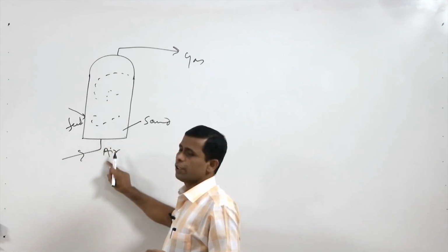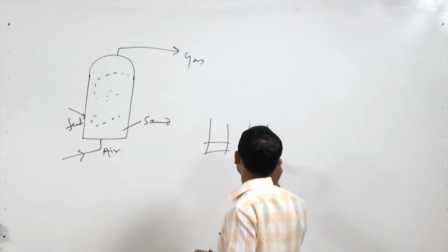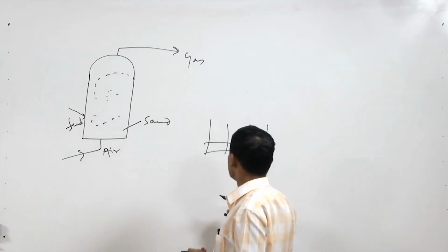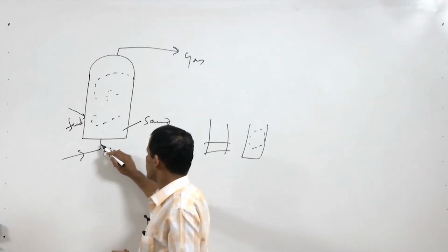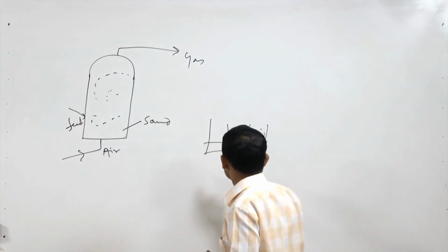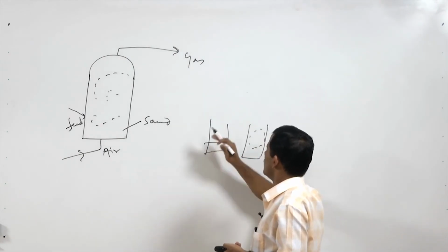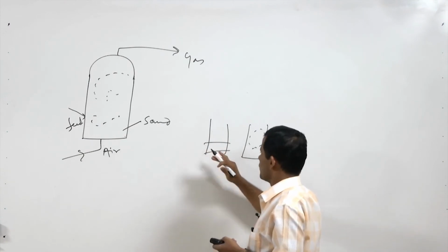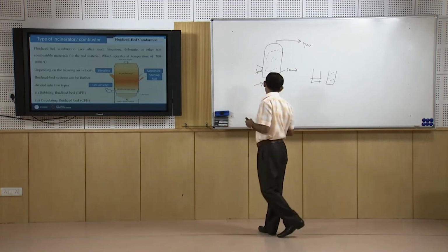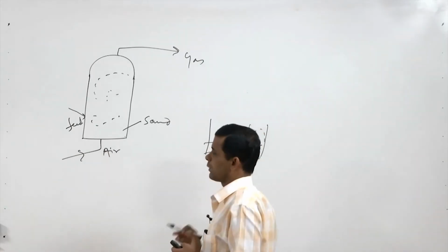The minimum fluidization velocity for incipient fluidization is what is able to separate the particles of the fixed bed enough from each other, so that their cohesion force is counteracted, and after increasing the air velocity further, fluidization will take place.